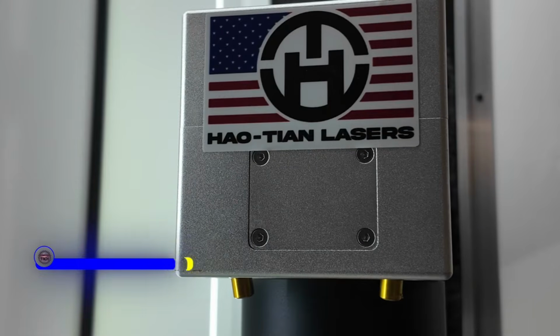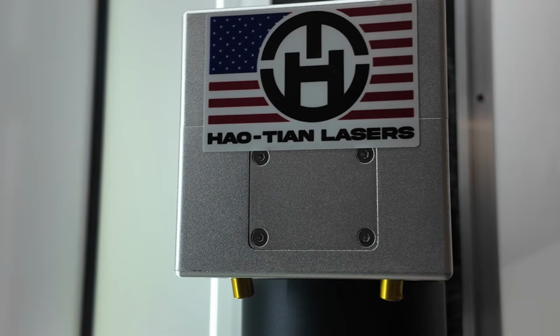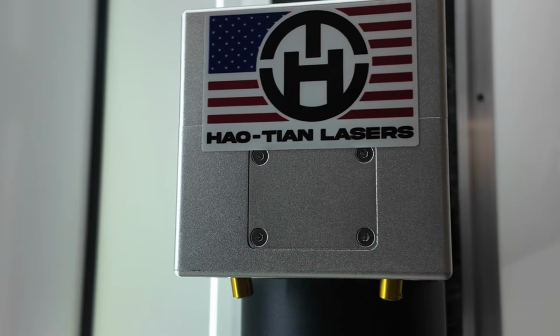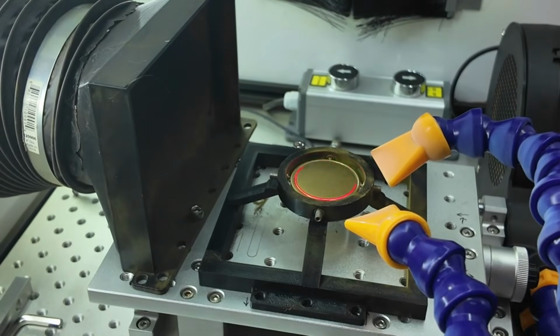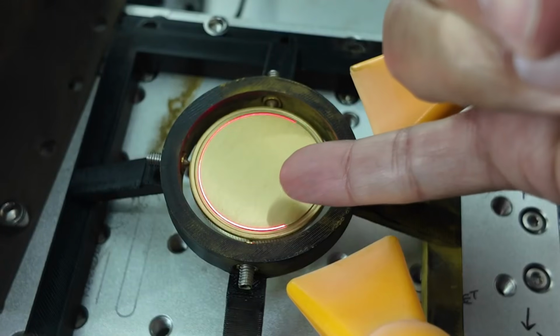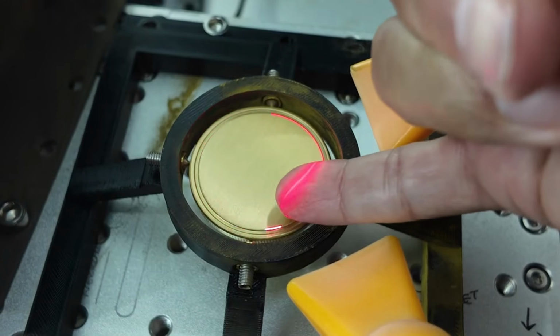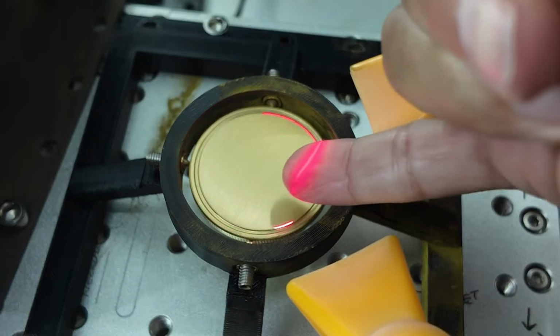All right, we are here at the fiber laser. Like I mentioned before, we are going to be using my Tian 80 watt JPT fiber laser. And as we scroll down here, we can see the setup that we've got going on. And this is just a little trick. If you put your finger above your framing, you can see if you're right on that line or not. It helps you get positioning.